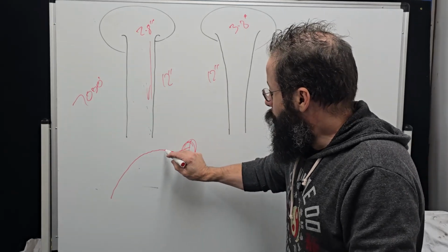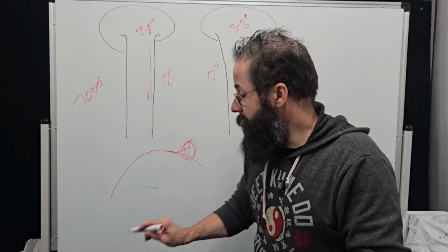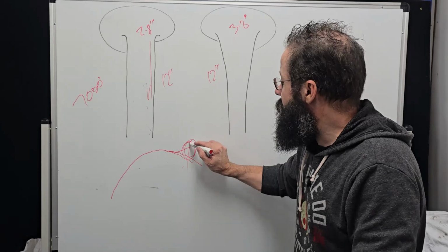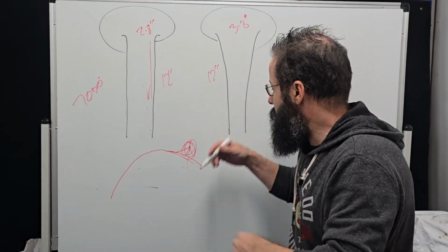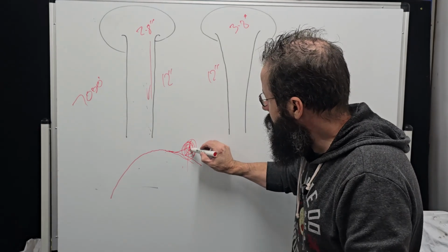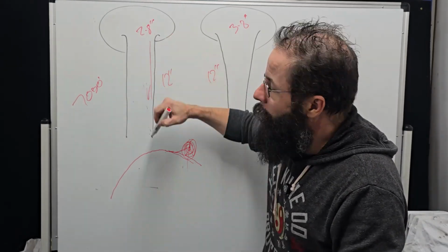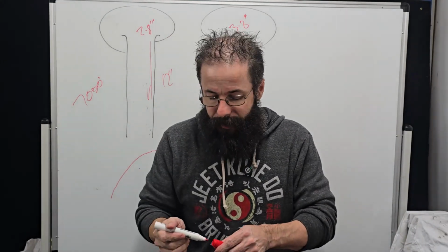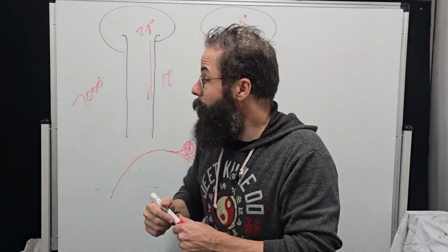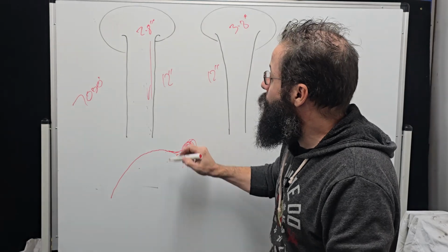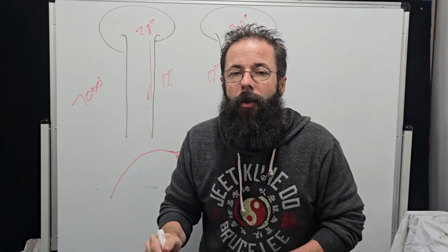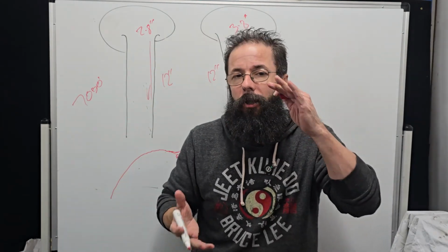So we're losing volumetric efficiency, and then bam, all of a sudden we see a spike just as we turn the dyno off. And I've seen this quite a few times. Well, that spike was your resonance. That was your harmonic factor. Now, the problem with the parallel runner is we're choking the engine. We're not optimizing that runner length, the point of having the longer runner.